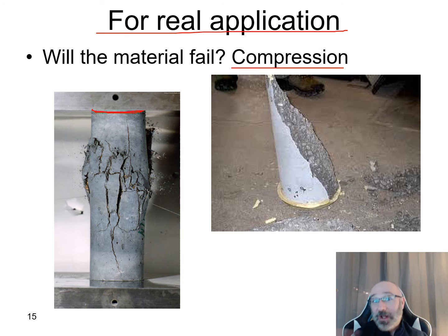So just a real application of why we may want to take a look and do some compression testing. We can go into that bridge deck and drill out these core samples and take a look at that. We can run these tests on there. We can back out our information, find out maybe there's a better mix, maybe there's a better concrete that we could use. The more information we gather, the more data we collect from this, the more we can categorize these. So this is a real application, speaking of material failure.